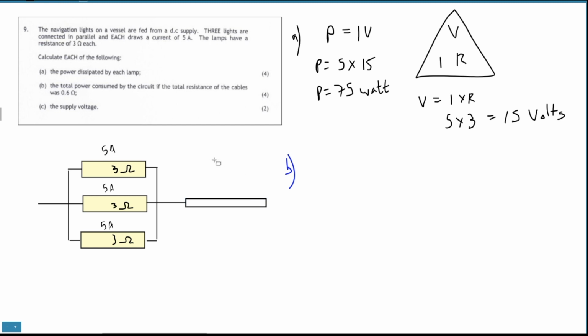I'm actually going to model my cables as being another type of resistor, a big fat resistor out here, a big fat cable going around. And then this will be connected to a power supply, which I can't see or don't really care about either. But just for the sake of completeness, it will look something a bit like this. This will be my cable. I can model that as my cable. Because if you're running something over a kilometer or 500 meters, then the cable has resistance. We do that later in another example. So it will actually have a resistance of 0.6 ohms.